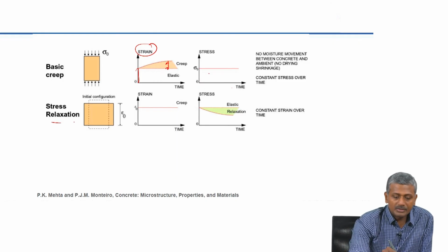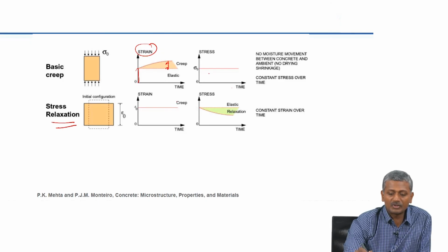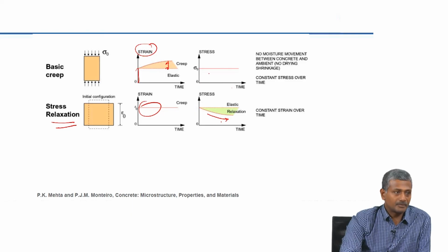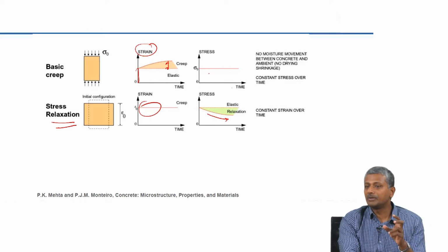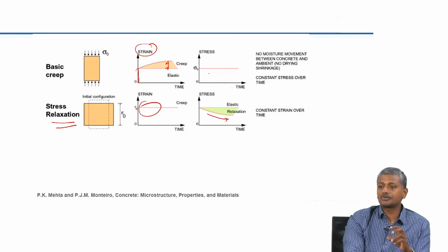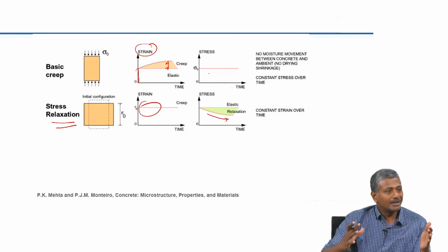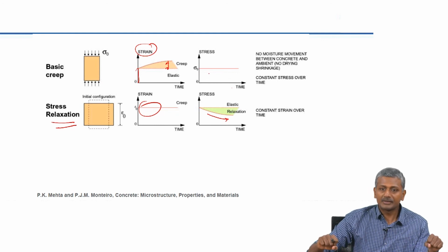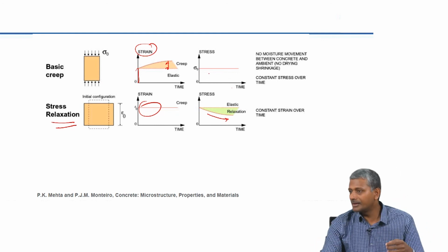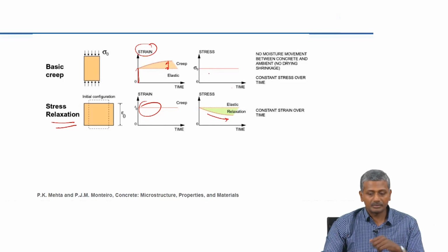The stress relaxation experiment is performed with a constant strain, monitoring the drop in stress with respect to time. Stress relaxation and creep can both play a significant role in the loss of pre-stress in pre-stressed concrete members. Creep in concrete and stress relaxation in the steel both lead to a reduction of the amount of pre-stress that the concrete has.